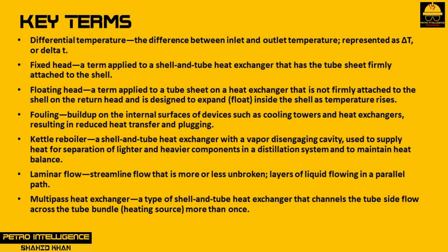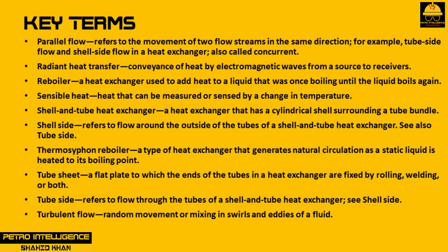Multipass heat exchanger is a type of shell and tube heat exchanger that channels the tube side flow across the tube bundle or heating source more than once. Parallel flow refers to the movement of two flow streams in the same direction, for example, tube side flow and shell side flow in a heat exchanger, also called concurrent.